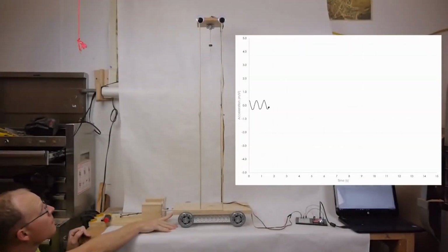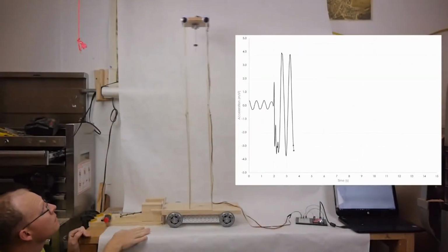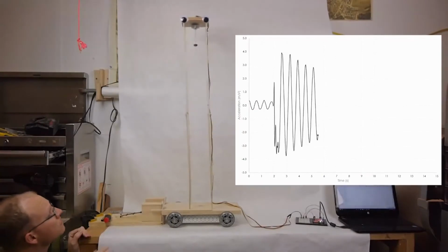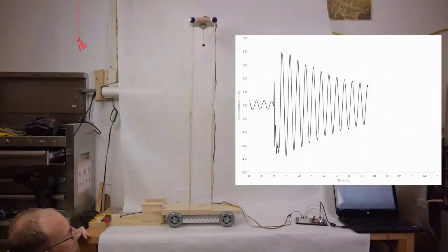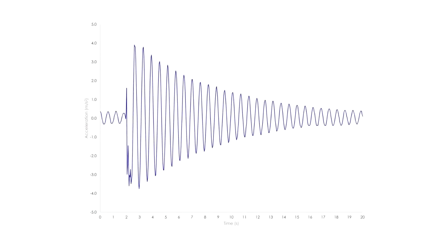If we lock the pendulum and set the building swaying, we can get a sense of how it would perform with only the building's own natural damping. Plotting the acceleration response, we can see that the model experienced the maximum amplitude. We can also see that the building has some natural damping just due to the internal friction in its movement. Otherwise, it would just sway indefinitely.